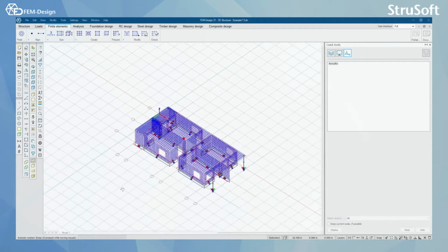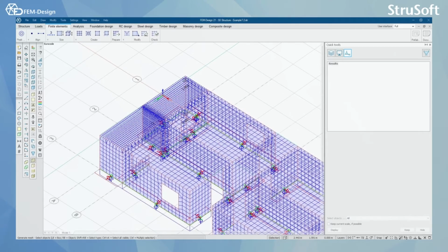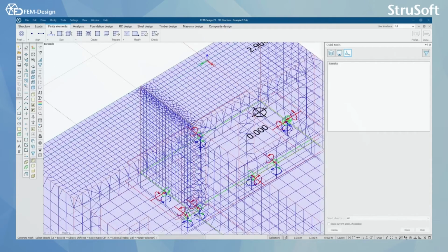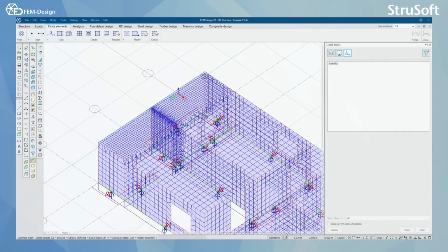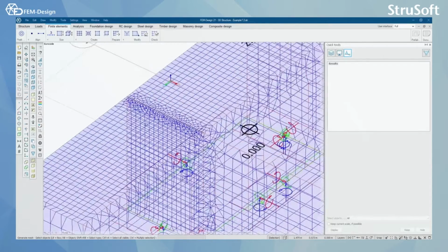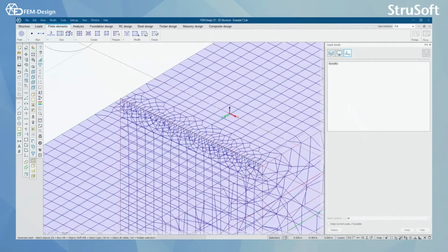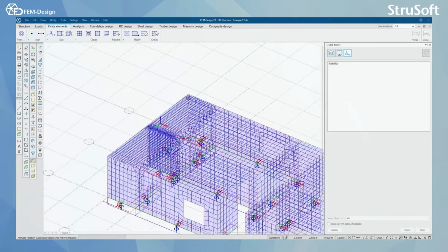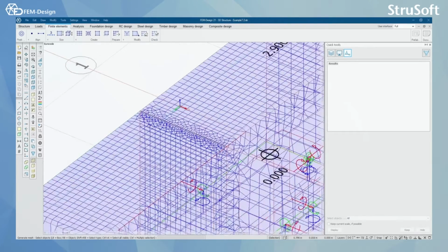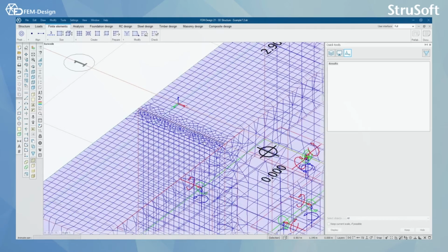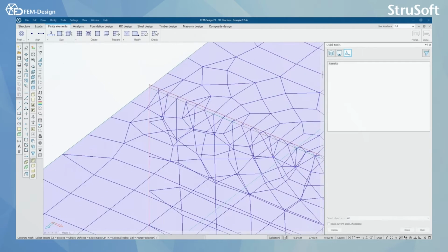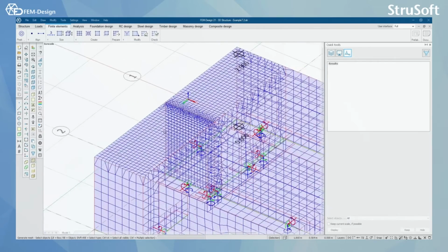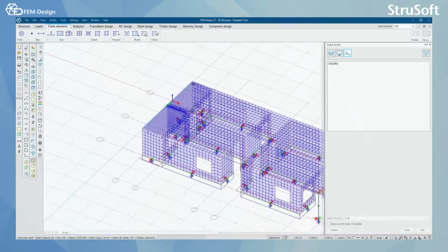And here I can actually see that here's a mistake that wouldn't stop the calculation, but whenever you see that the mesh size is getting very small at a specific place, it probably means that there is some minor modeling error, which if you have a lot of these in your model, it means that your calculation will probably take too long and it's too time dependent design work. So I'm going to zoom in and I can actually see that this one shell is being modeled a bit too high, and it will cause this mesh to be a little bit too dense over there.